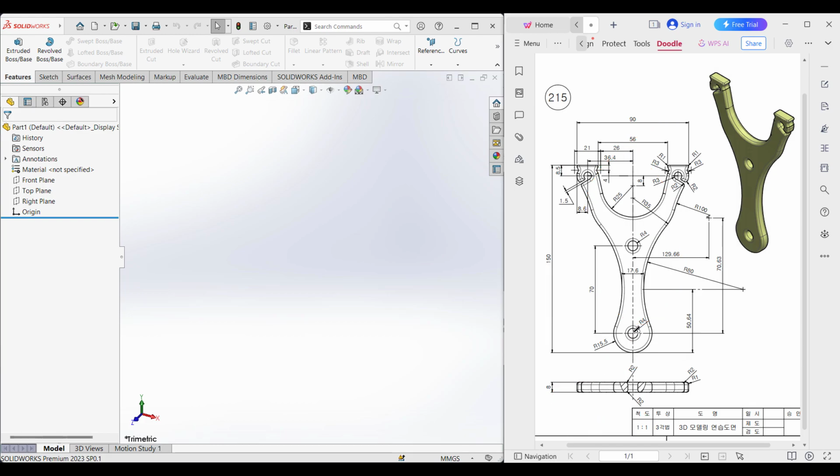In the front view, we can see that we have a circular profile here, and this circular profile has a radius of 15.5 unit. So first of all, I'll draw a circle of 15.5 unit here. After that we can see that we have another circular profile like this one, and this circular profile has a radius of 80 unit, and it has a distance from this center line.